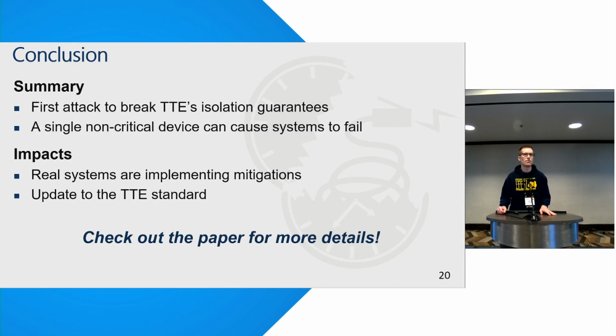Very interesting. So you have to be exceptionally lucky for this to work because you don't want to screw up the Ethernet preamble for the synchronization of the devices. You have to hit the header at the exact right moment and leave the rest intact so that the CRC still works out. Can you say something about the success ratio? How many failed attempts do you need?